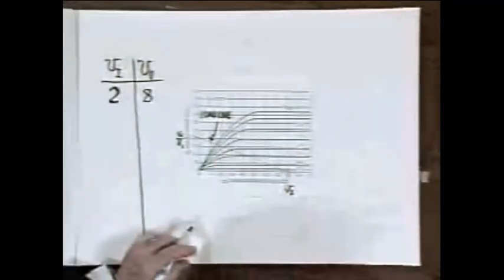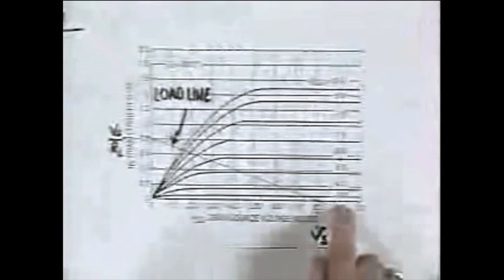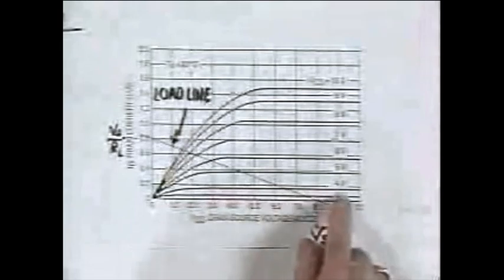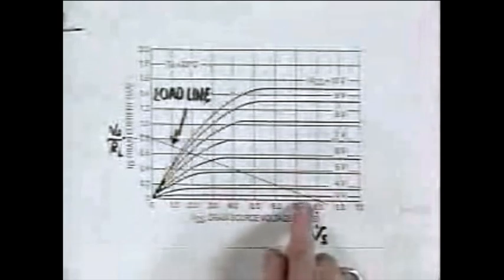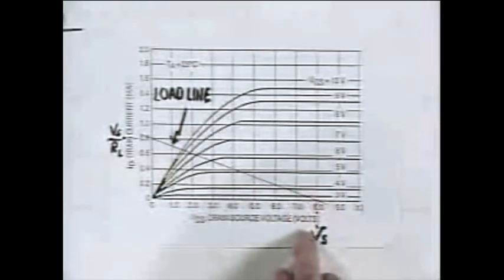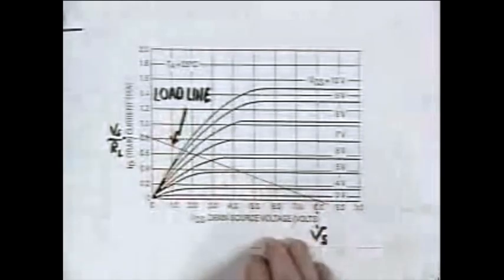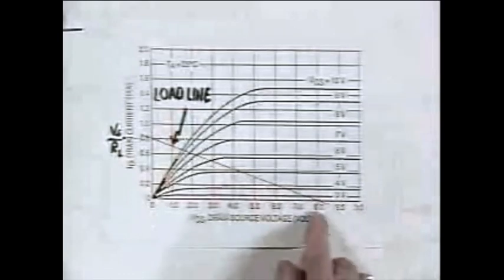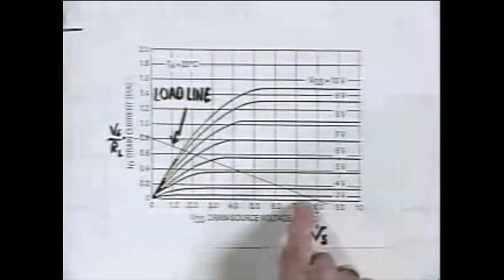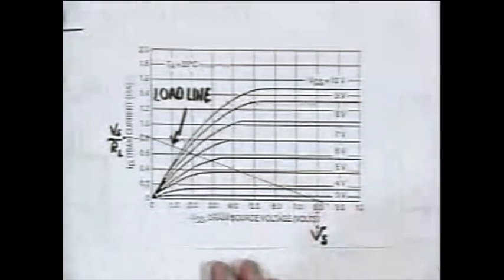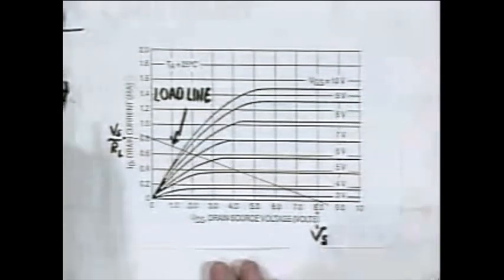And this then can be done by following right up along the line for each intersection of a transistor characteristic curve with the load line. There is a particular value of VGS and correspondingly a particular value of I sub D. We're plotting VGS equals V sub I. So if I go up here to 3 volts and look, eyeballing that says that the drain to source voltage is about 7.4 volts for 3 volts on the input. This is about 7.4 volts.